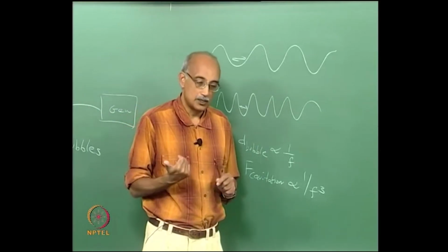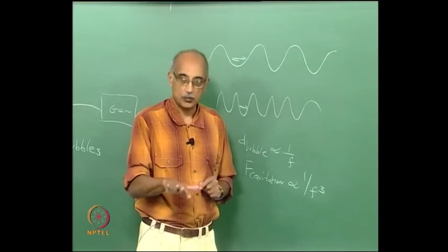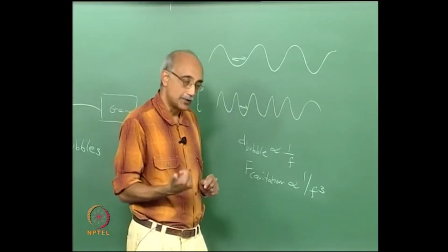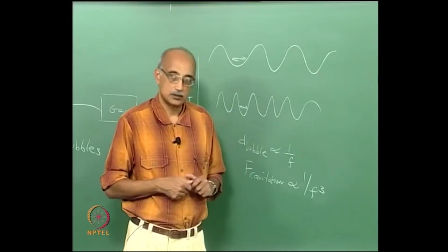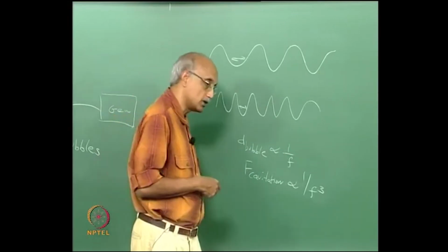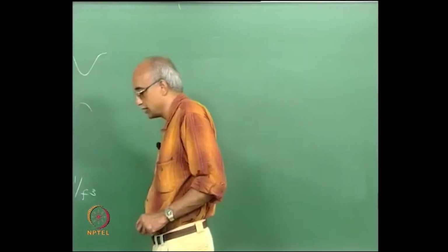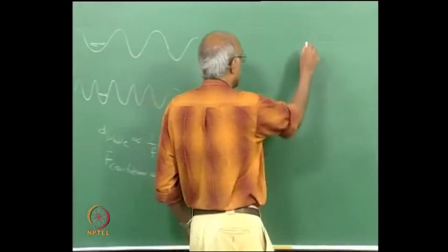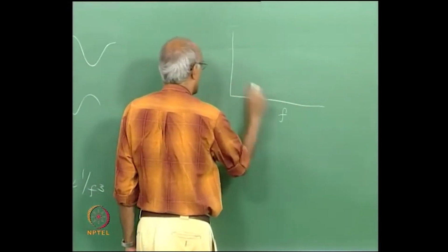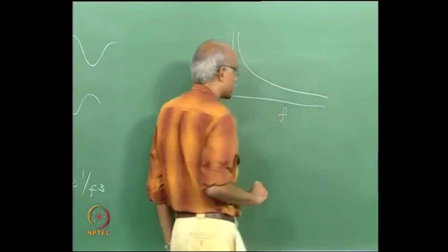So, one reason not to use too low a frequency in surface particle removal is to avoid damage to the substrate. The other reason is that if you look at that boundary layer thickness that I had sketched earlier, that also has a dependence on the frequency. The thickness of a boundary layer around an object in the presence of an acoustic field has this type of dependence.